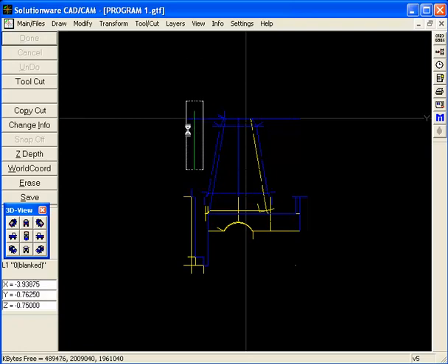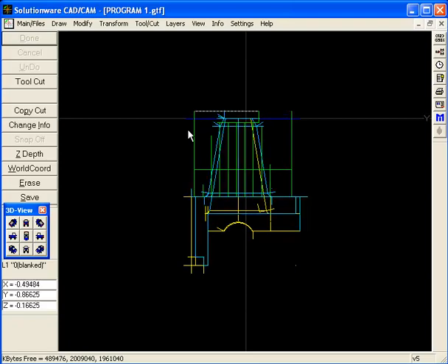Okay, so after calculating the toolpath, you can see now from this perspective the tool's going down to the first peck, which is Z 750 thou deep, and I'm going to speed up. You can see that it's staying off the part, then it goes down to the full depth. So anyway, that is how you would go about cutting this particular part and just the upper part of these nozzles using a projected macro cut.